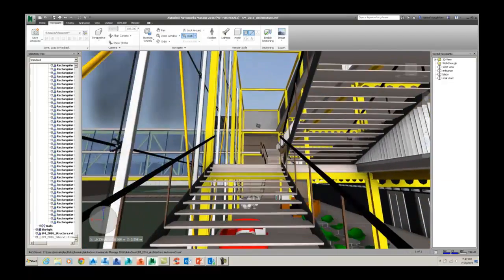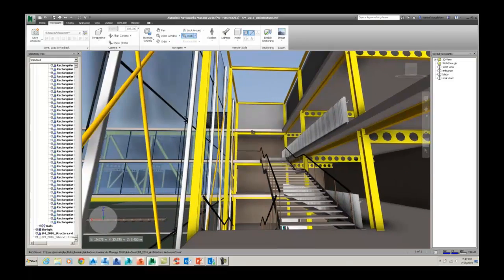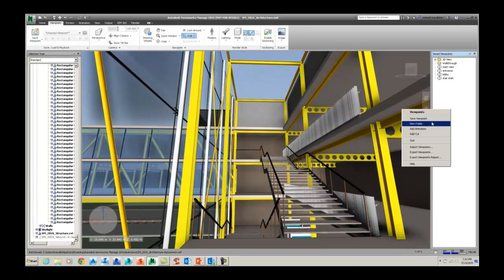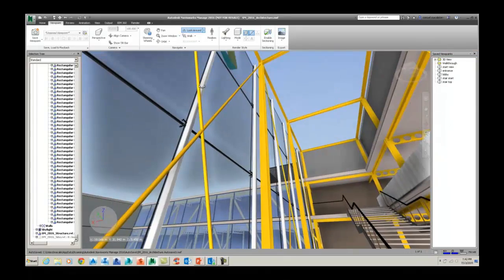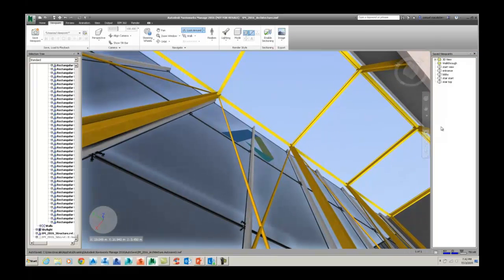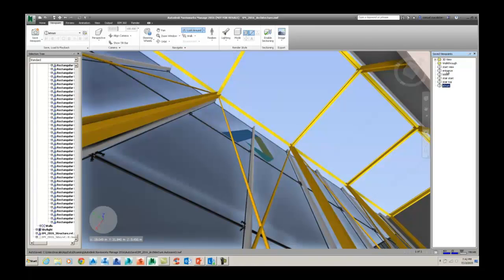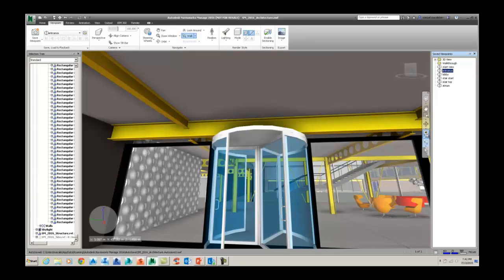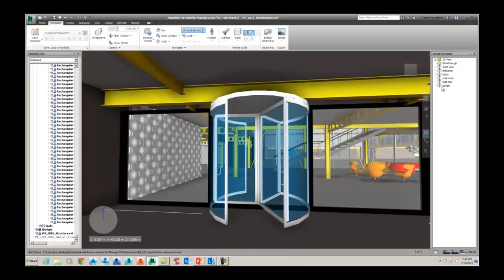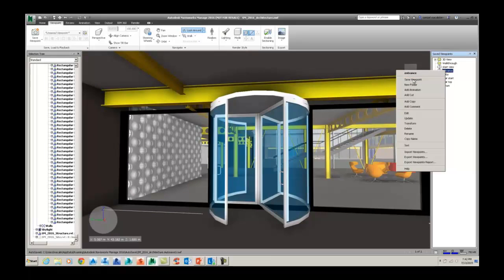With that turned on, we can now use the gravity tool to walk up the stairs and finish at our final arrival point here at the top of the stairs. And then the one final adjustment is doing an Atrium View here inside the Autodesk building. So now we have say half a dozen views saved inside of Navisworks, and we want to fine-tune them and then stitch them together to create an animation.